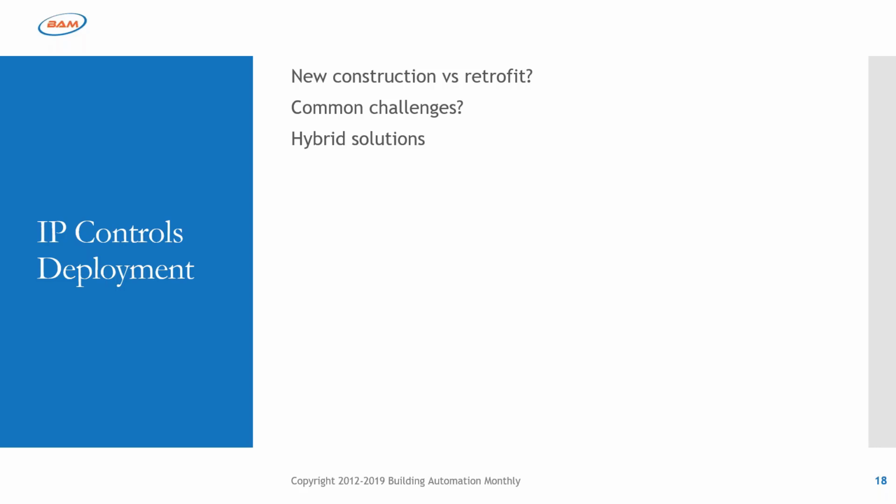Well, yes, this is no different than if you know you're going to be doing a TI and you know that there's going to be controllers somewhere. So you string up some MSTP cable up in the ceiling, and then you later extend it to wherever the controller is.